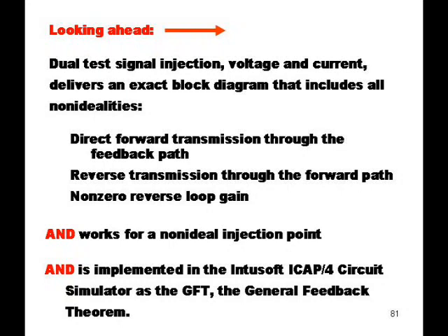That, of course, is true at low frequencies. But at high frequencies, the forward gain drops off. And in fact, the loop gain ultimately crosses over unity and gets to be less than 1. In other words, the forward path tends to become a passive network rather than an active network. So the transmission in the two directions easily can be comparable at high frequencies.